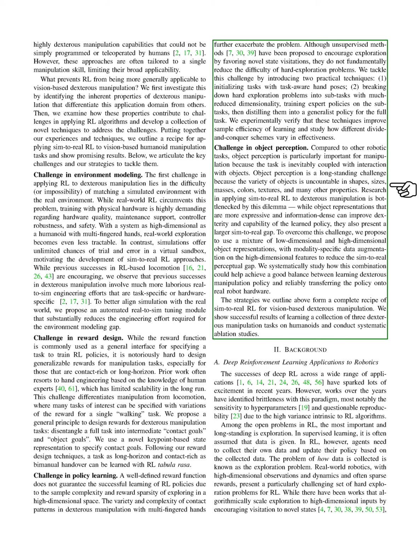We address this by introducing two techniques: starting tasks with informed hand poses and breaking down difficult exploration tasks into simpler subtasks, training expert policies for these, and then combining them into a general policy for the full task. Our experiments show that these methods enhance learning efficiency.